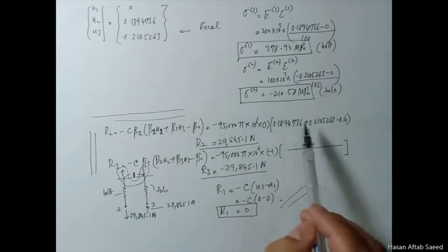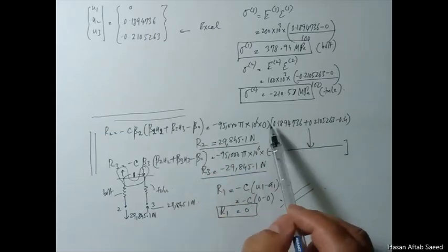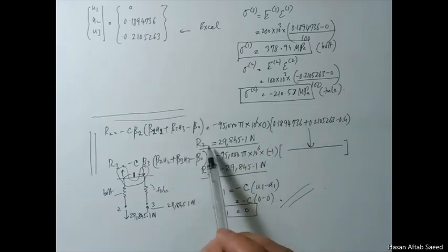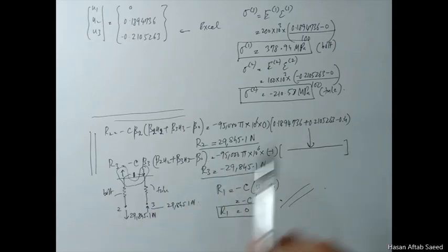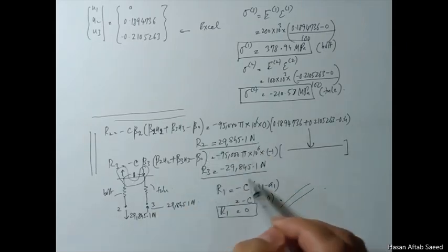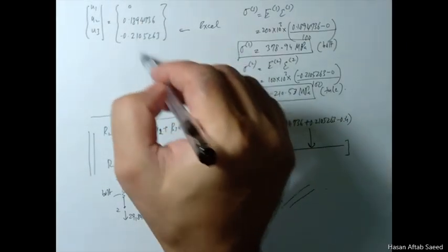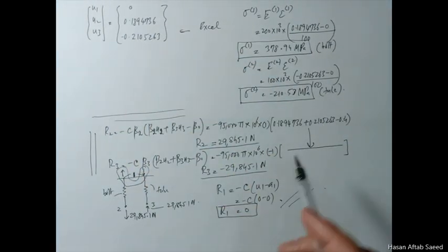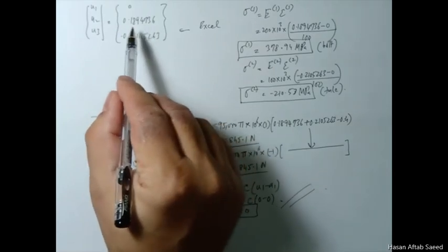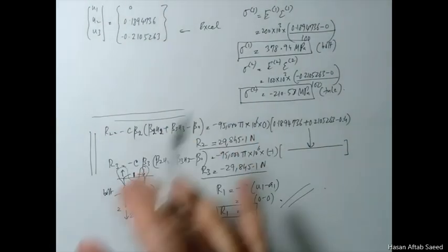So even a slight inaccuracy here will cause the reaction forces to be very much away from the real forces. So you should be very careful about using exact figures here. Again, this is of limited value as far as practice is concerned, but it's good practice, as mentioned earlier, to use double precision arithmetic and to retain as much information as you can to get best results.